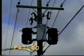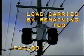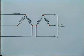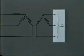The three-phase load must now be carried by the two remaining transformers. In this situation, an unbalanced transformer connection must be used, such as the open delta. In the open delta configuration shown here, only two single-phase transformers are used, but they can supply three-phase loads.